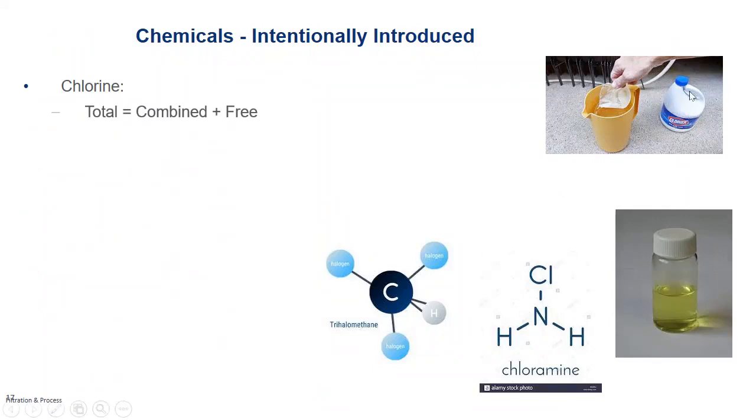Chlorine has a 98% kill rate in a specific amount of time, and chloramine is around 80 to 85%. But it sticks around longer. So it has a cost benefit ratio that's better than chlorine, especially in warm surface water sources where this is important. About 62% of municipalities now use chloramine in one form or another in their municipal treatment plants.